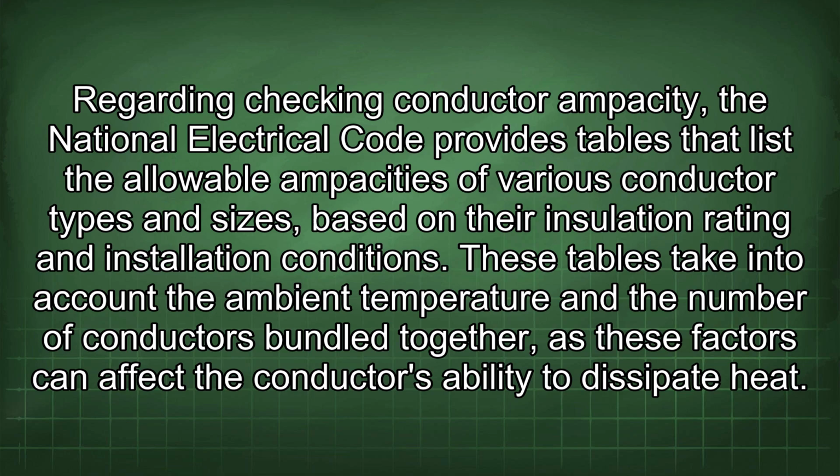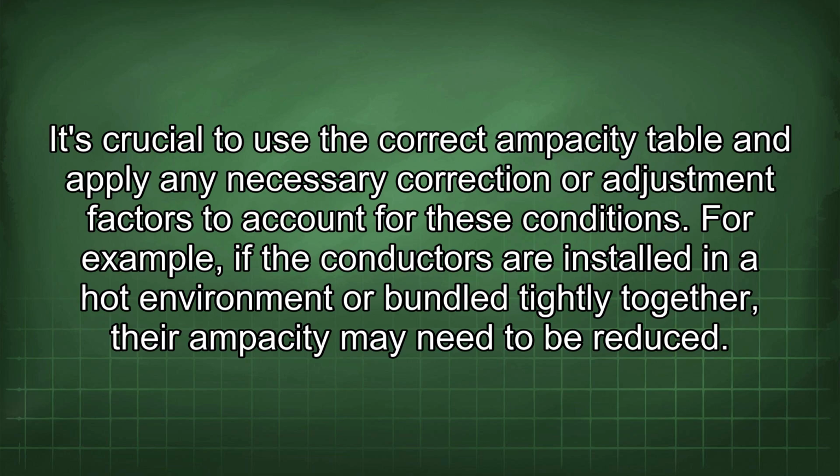These tables take into account the ambient temperature and the number of conductors bundled together, as these factors can affect the conductor's ability to dissipate heat. It's crucial to use the correct ampacity table and apply any necessary correction or adjustment factors to account for these conditions. For example, if the conductors are installed in a hot environment or bundled tightly together, their ampacity may need